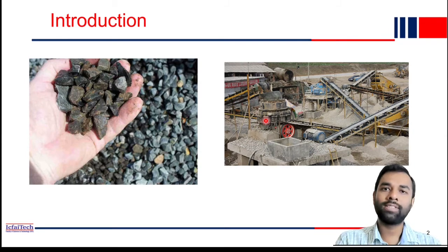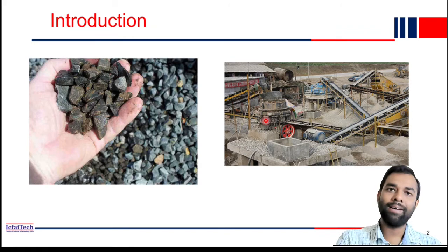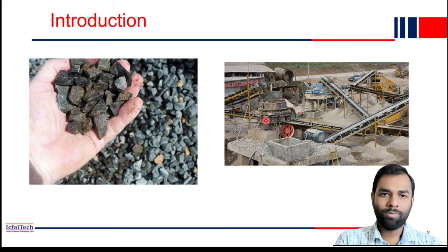Even for road construction, when we make our subgrade, at that time we use bigger dimensions of aggregate, right? But when we construct slabs, beams, columns, at that time we use smaller dimensions, maybe 20 mm diameter or 12 mm diameter aggregates, right? So while crushing the aggregate, we have to get the proper size of aggregate, because that is what is required in our construction purpose, that only we should make, right?